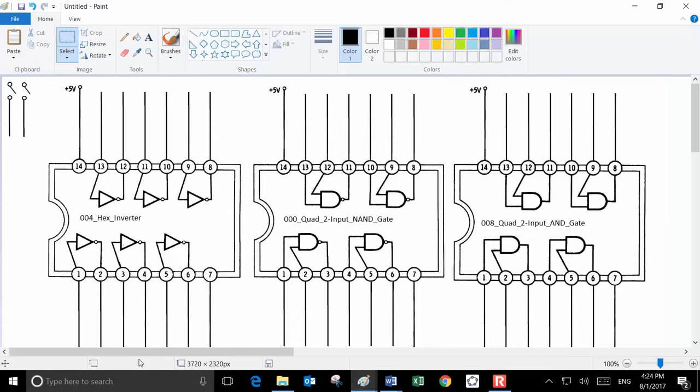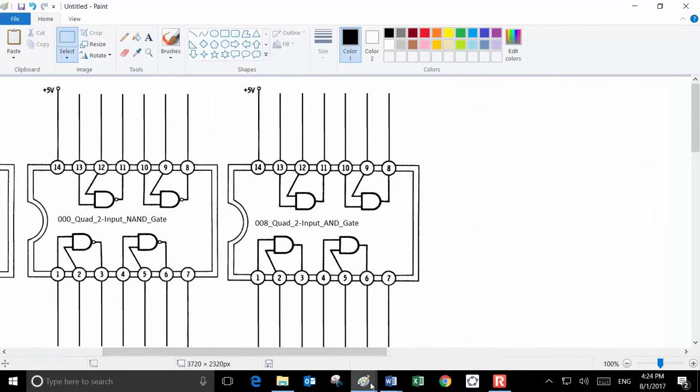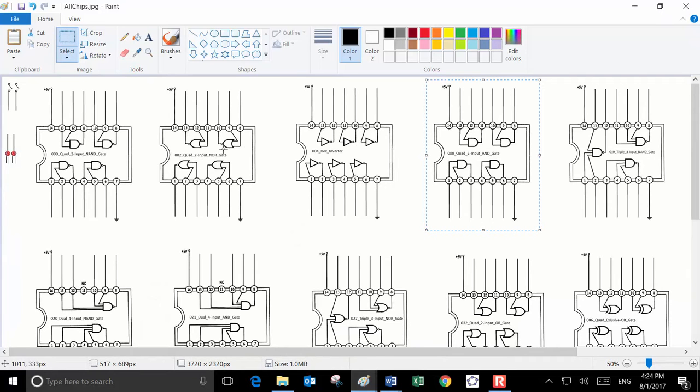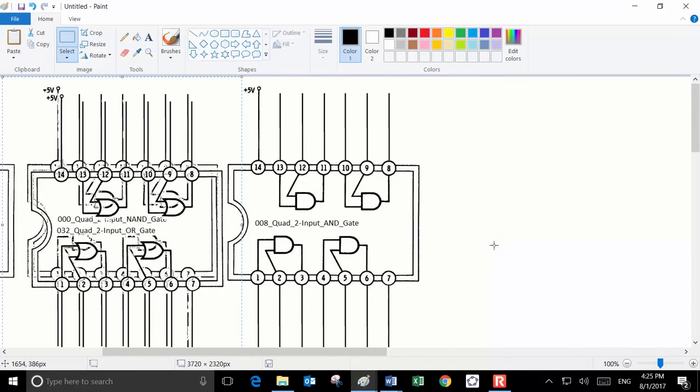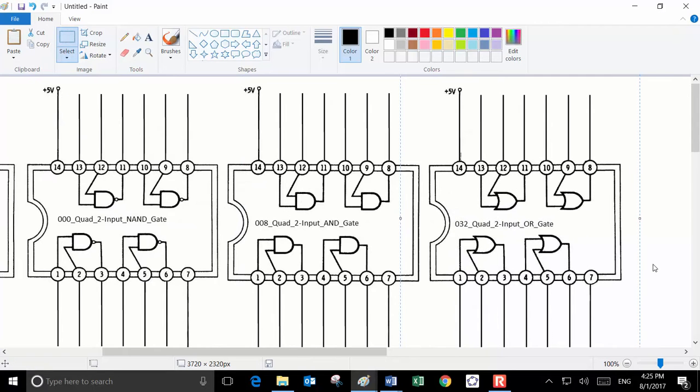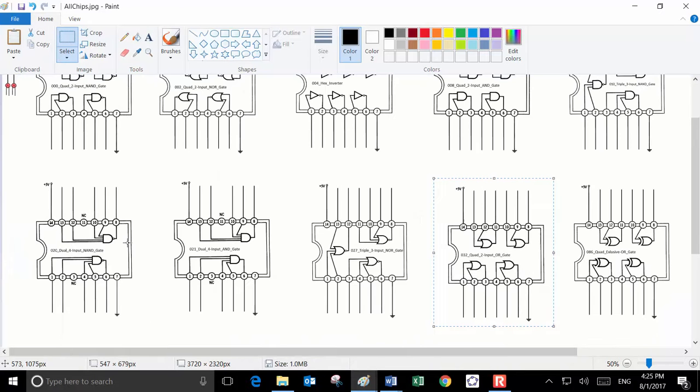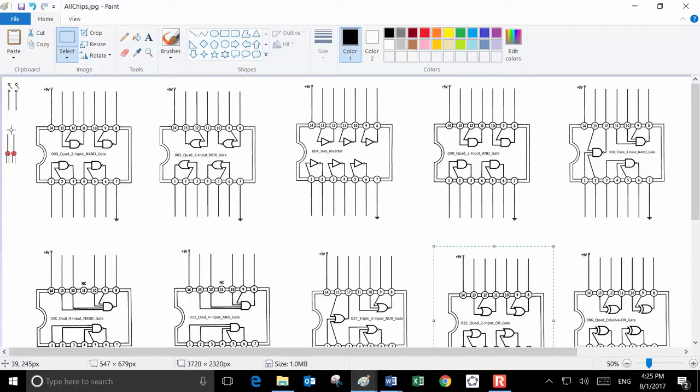Then we need an OR gate, as you may recall. So that's a NOR, that's not going to cut it. We need an OR. And triple NOR, there's our OR. Copy that into place. And lastly, we need an LED for our output, but we only need 1 of them. So I'm going to just copy 1.